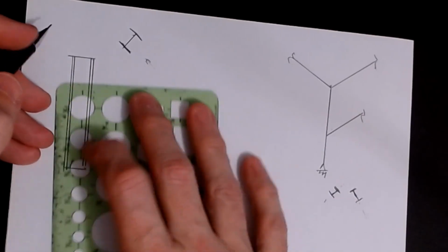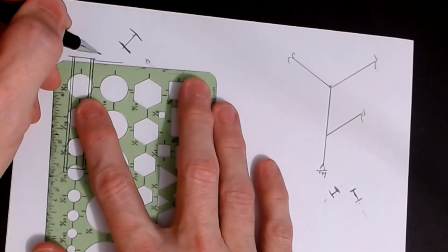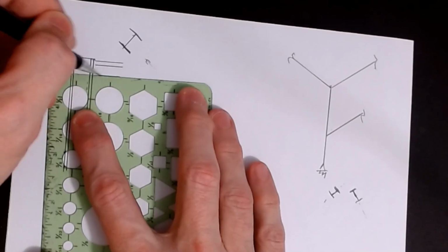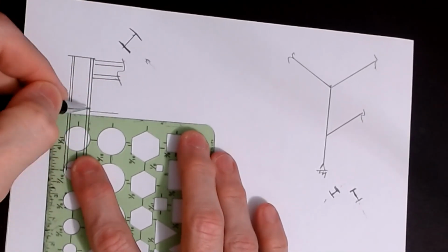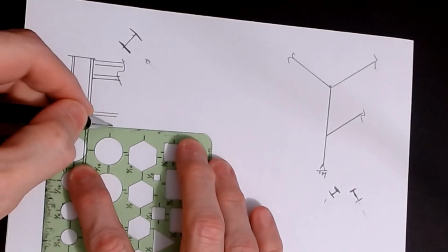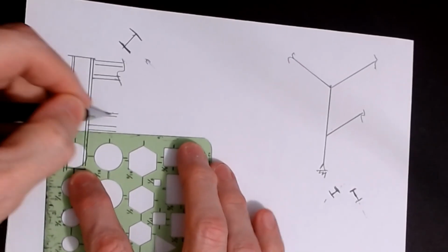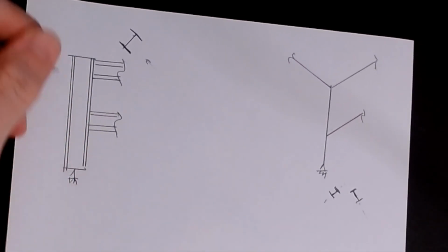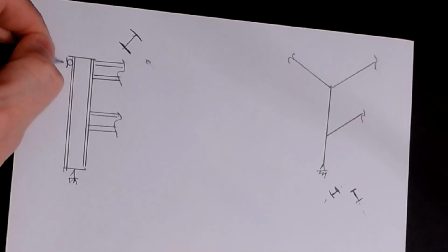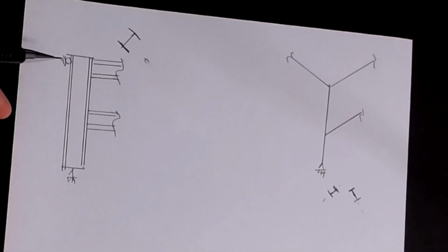Then at this height in the X direction, here's the beam at the roof, and then here's the beam at the mid height. It'll look just like that, and then we assume that this is pinned. And just for the sake of argument, I'm going to put a roller on that just to say that this building is not subjected to side sway.